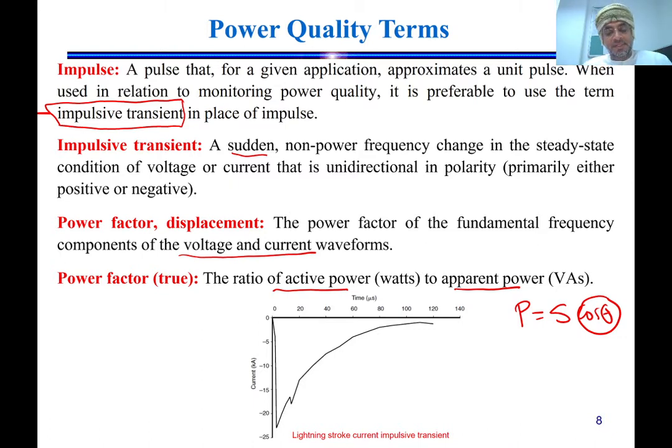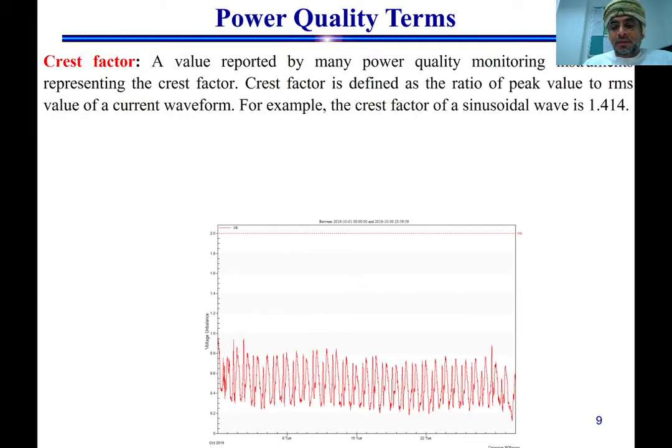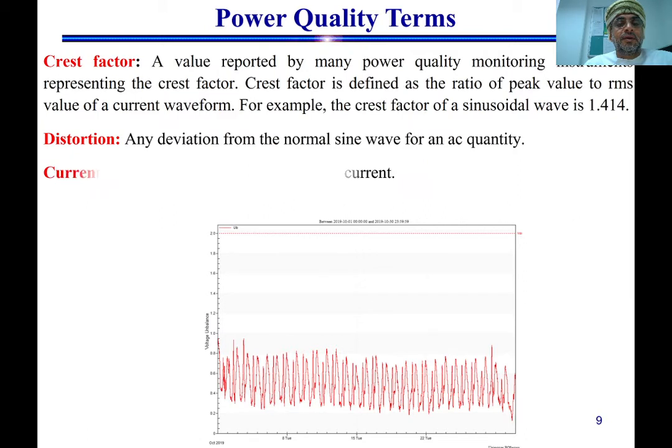And again, we're gonna take some tutorial problems later on, and we're gonna show you how to calculate the displacement power factor and the true power factor. Of course, over here we are talking about harmonics, okay? We're talking about a waveform that includes harmonics. If we are looking at a waveform that is without the harmonics, of course, those will be the same. The power factor and the displacement factor will be identical.